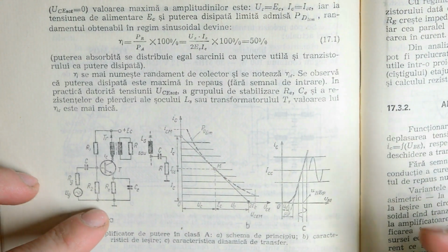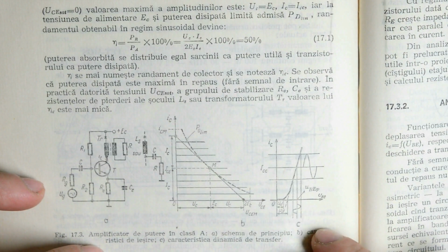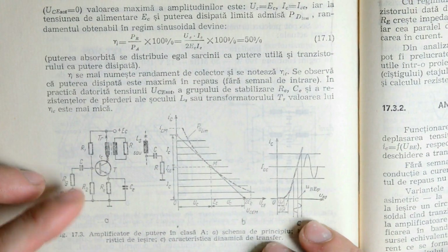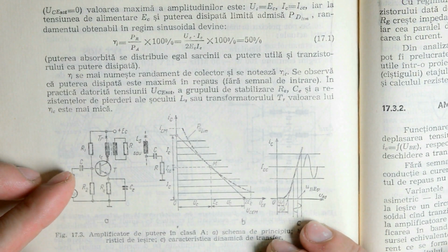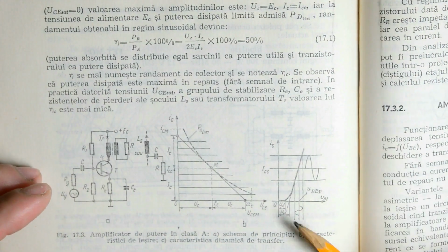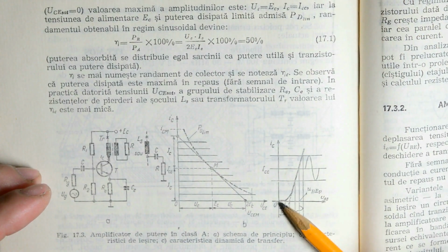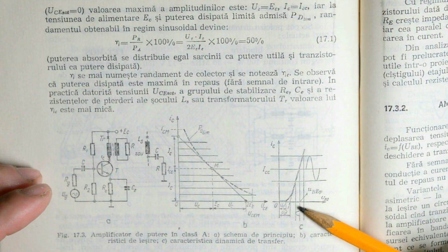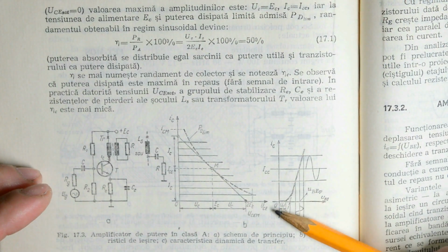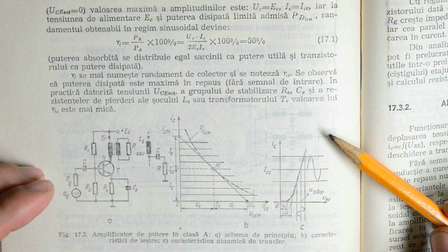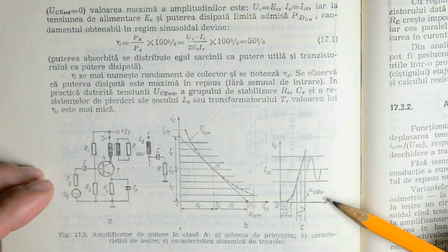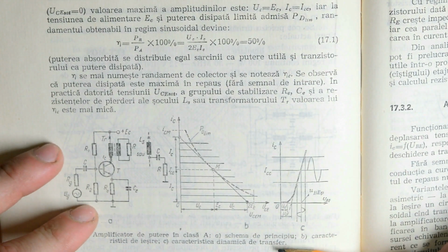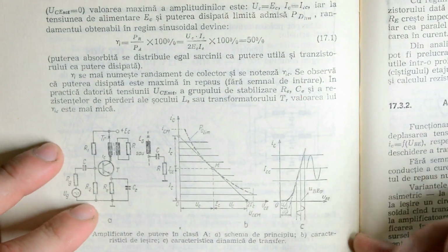Well, for that we need to analyze a bit how the transistor works. The transistor has three modes of operation. Cutoff, in which the base signal is too small to actually switch the transistor, so you get a certain base emitter voltage, but you have no collector current. Then you have the active region, in which the input signal actually creates an output signal on the collector, and then you have the saturation mode, in which the base emitter signal no longer creates any more variation on the collector.